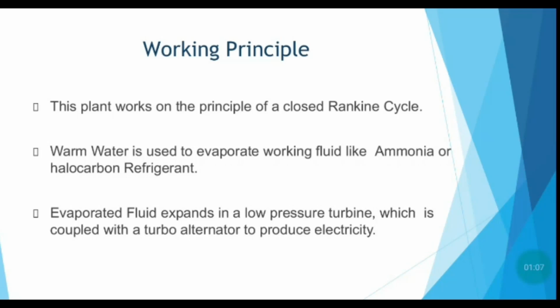The working principle of OTEC. This plant works on the principle of a closed Rankine cycle. Warm water is used to evaporate a working fluid like ammonia or hydrocarbon refrigerant. The evaporated fluid expands in a low-pressure turbine, which is coupled with a turbo alternator to produce electricity.